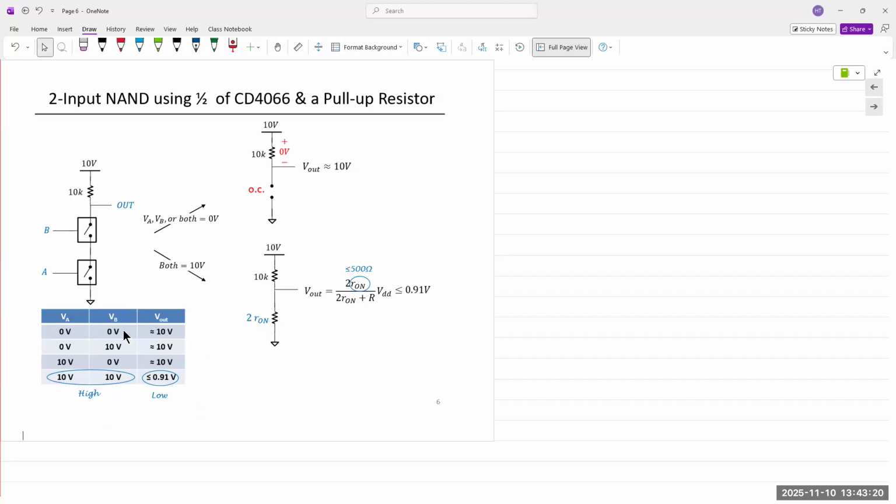So in terms of logic or binary numbers, you have already seen this before, right? In 133, the NAND gates and the operation. This is a look behind the curtains, meaning if you wish to implement this using circuits, that's how this would work. So this would require two switches because a NAND gate is a two-input gate, except for the NOT gate, which is single input. All the other gates are at least a minimum of two inputs. So it uses two of the four switches inside the CD4066 chip. So it's half of the 4066 chip. All right, inputs are A and B.